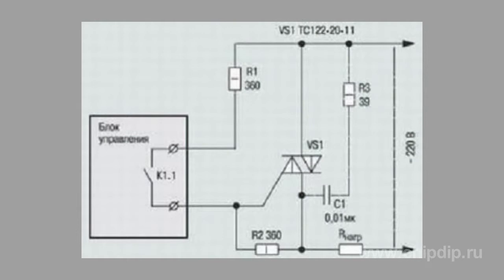and incandescent lamps. To avoid misoperation of triacs caused by noise and strokes created by motors, circuits using four-quadrant 4Q triacs must have additional protective components. As a rule, this is a damping RC chain between the power electrodes of the triac. It is used for limiting the speed of voltage change. In some cases, inductance is necessary to limit the speed of current change at the moment of commutation. These components increase the cost of the device as well as its dimensions. Besides, they can also reduce its reliability.